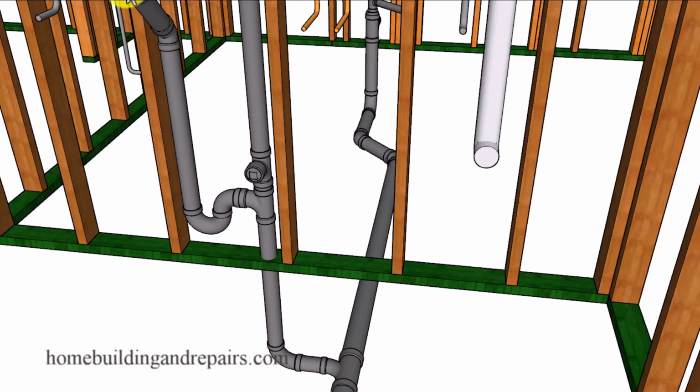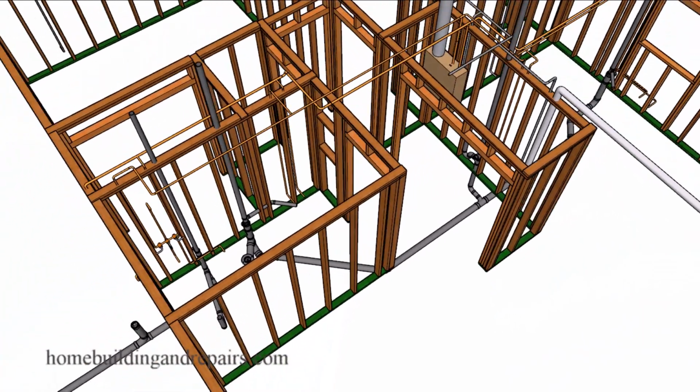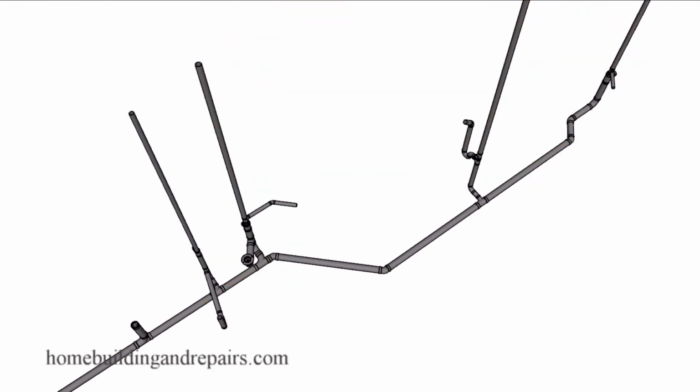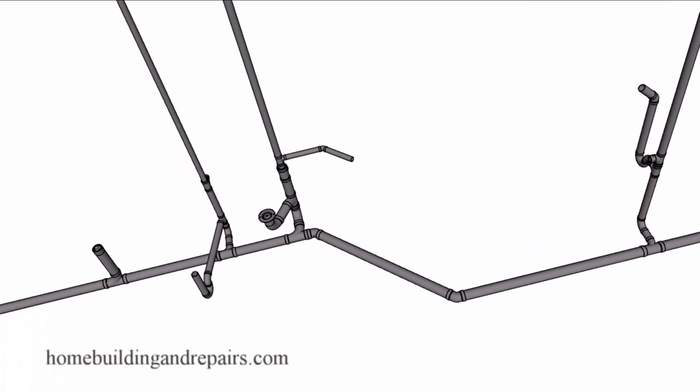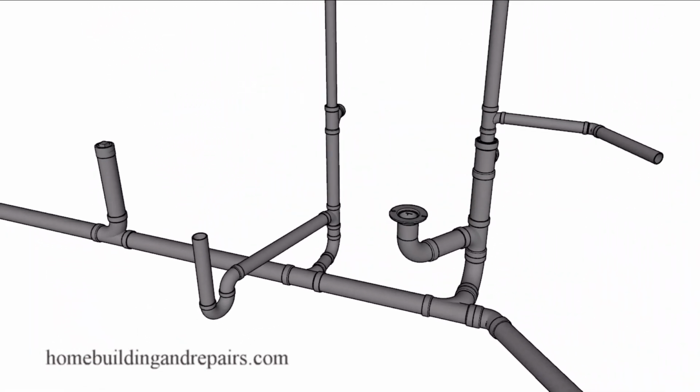And by now, hopefully you're starting to wrap your mind around what I'm talking about, with a clear understanding that if you don't know what your pipes look like underneath your house, then you're going to need to do a step-by-step drain cleaning. Again, starting with the traps if that's easier, or clean outs if that's easier.